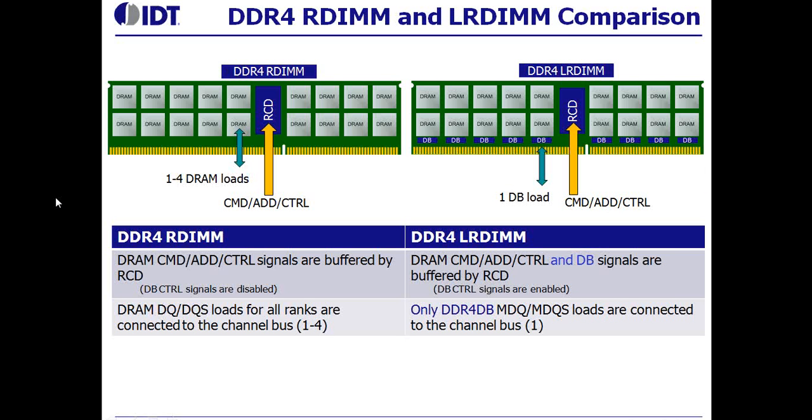This means that there will only be 1 load presented at the LRDIMM connector instead of 4, like there were on the RDIMM. This leads to better signal integrity on the data signals at the edge connector, also referred to as DQ bits on the edge connector. Having fewer loads at the connector is why LRDIMMs can be populated into your server with less degradation in performance. Imagine 3 RDIMMs populating a server.